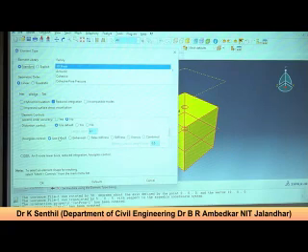This is the one thing. So you have to maintain the internal angle between any two lines. It should not be below 60 degrees, and it should not be more than 135 degrees. Okay, fine. Second thing, while running this analysis, there is a possibility of distortion because of excessive stress.